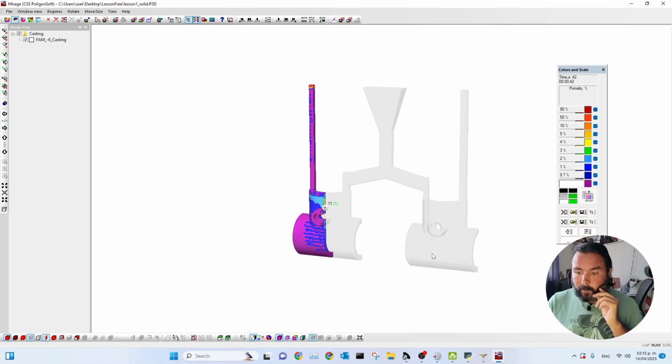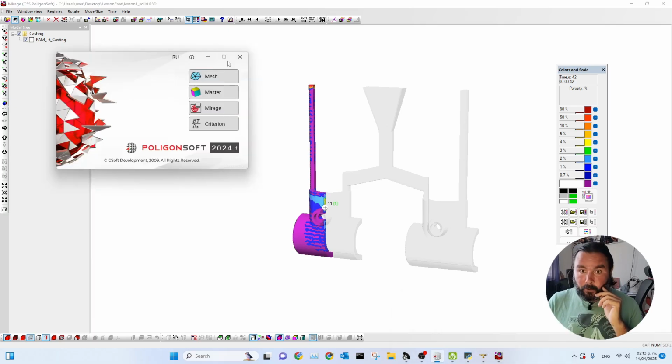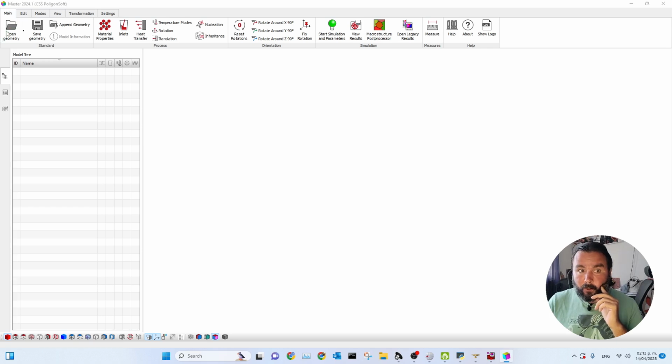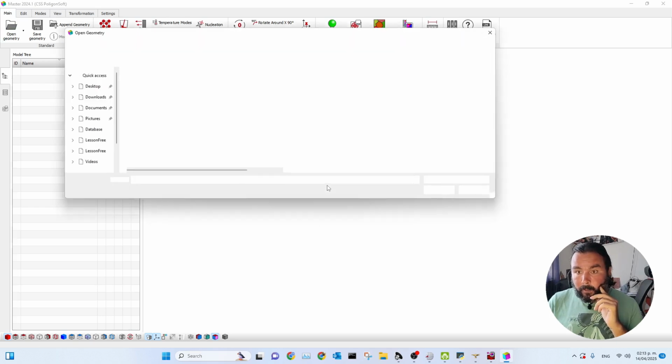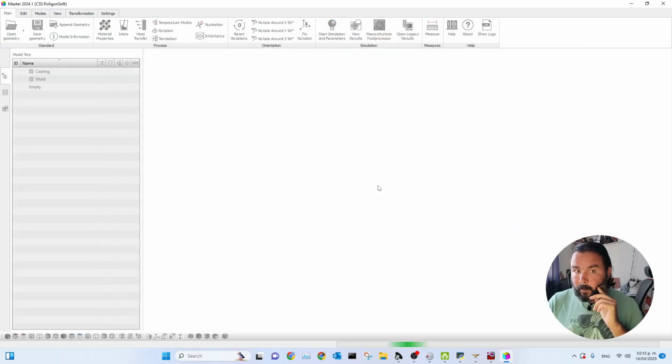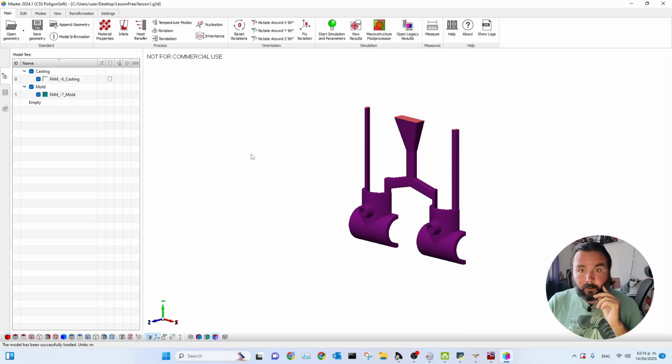Actually, in a real job, we would have needed to make several more changes. For example, I almost always recommend running the calculation for various temperatures, starting from the minimum temperature and ending at maximum temperatures, and in this way find the optimal temperature for our casting, the temperature that will allow us, with the lowest costs, to achieve a part with the fewest possible defects.